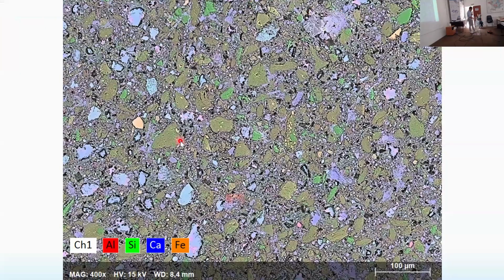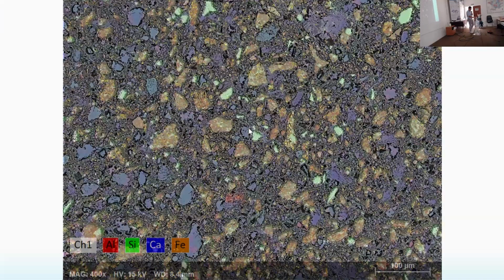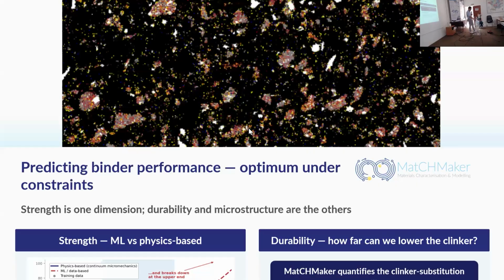You see again these bluish, reddish, bright particles, which are the traditional cement. But now it's blended with the calcined clay, which you see as this brownish patch. And also in green, you have the quartz. So again, we developed this segmentation tool. I just go through to visualize what is happening. And at the end, we end up with the segmentation of the calcined clay, which is going to shrink over time, but it may have different phases because clay is a multi-mineral material. So we want to assess which phase of the clay will specifically react. So this was helpful in this way to sharpen our understanding of the microstructure of the cement.